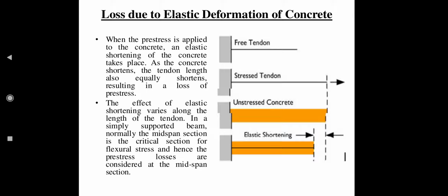So here the formwork is formed in the factory and the cable is placed within that framework. It is stretched within its elastic limit and both the ends are anchored. After that, concrete is placed over this tensioned tendon, as you can see in the third figure.